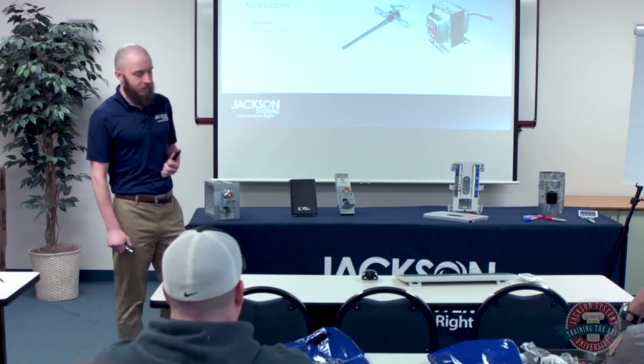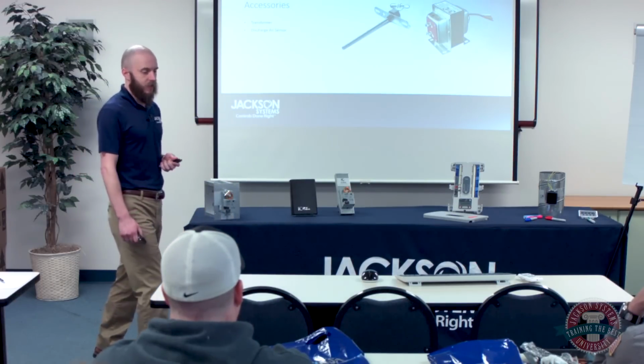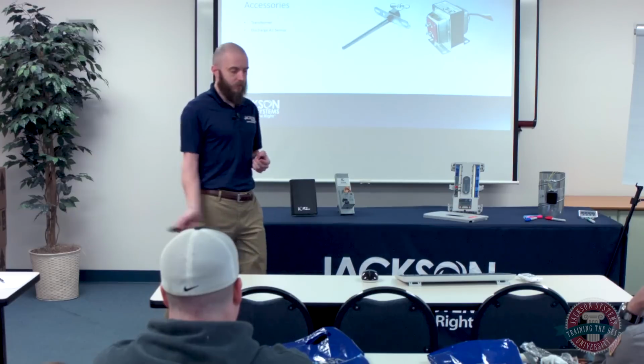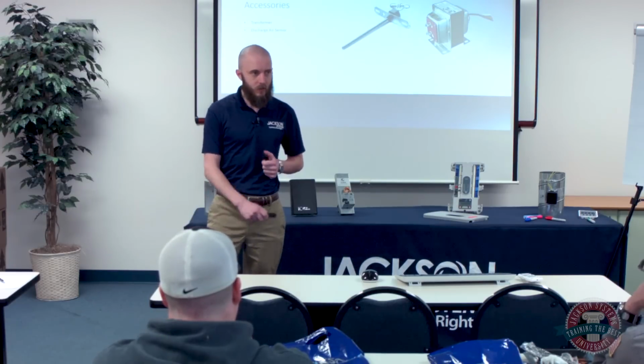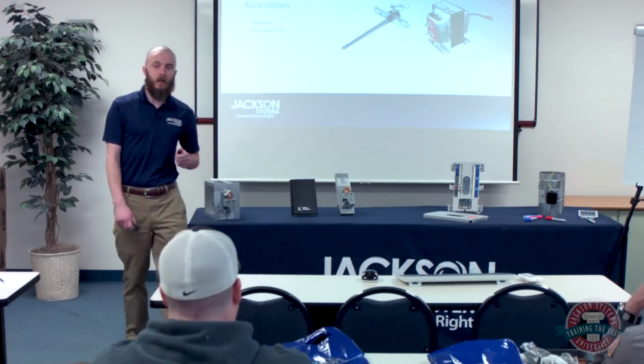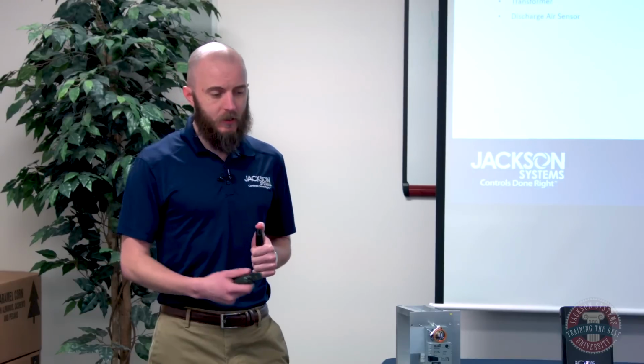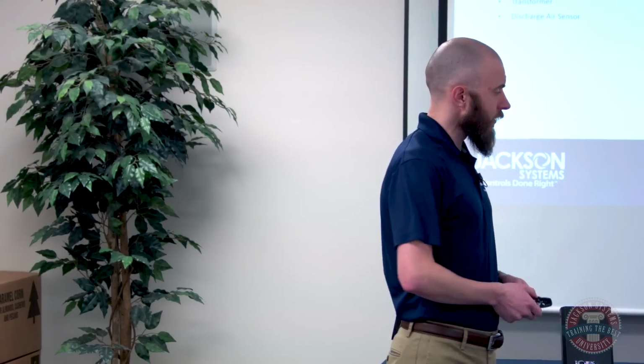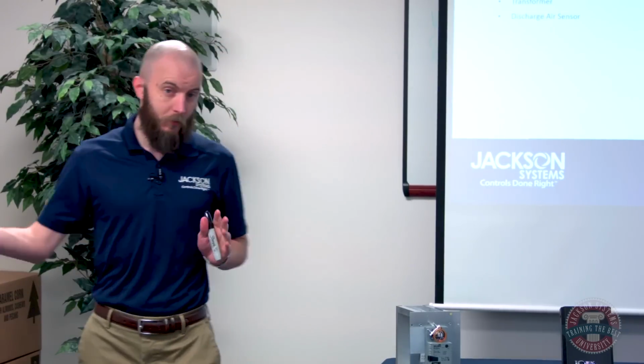And lastly, just know what accessories to get with your zone systems, whether they're discharge air sensors, return air sensors, outdoor temperature sensors if you've got a heat pump panel that's controlling a dual fuel system, and a transformer that is properly sized. Again, we typically recommend using a separate transformer from the equipment transformer, mainly because on most zone panels, you're going to have complete electrical isolation between your inputs and your outputs to your equipment.